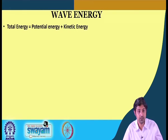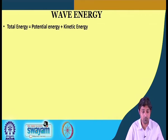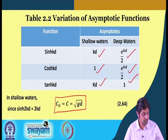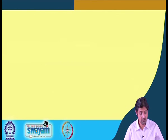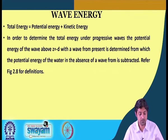Now, what is wave energy? We have discussed almost everything. We have discussed the particle trajectories, then we have discussed the group velocity. Now, we must go towards wave energy. So, total energy is potential energy plus kinetic energy. In order to determine the total energy under a progressive wave, the potential energy of the wave above z equal to minus d with the wave present is determined, from which the potential energy of the water in absence of the wave is subtracted.